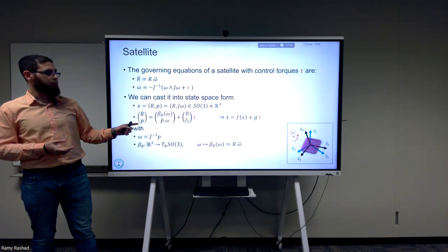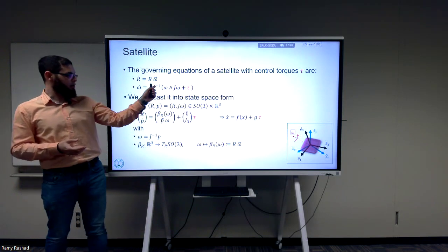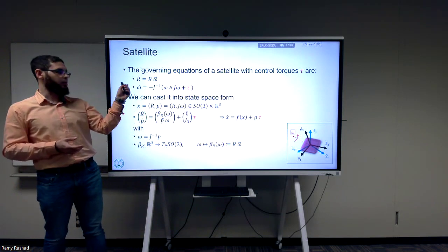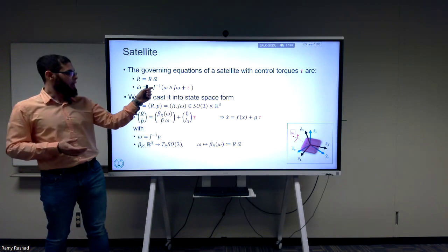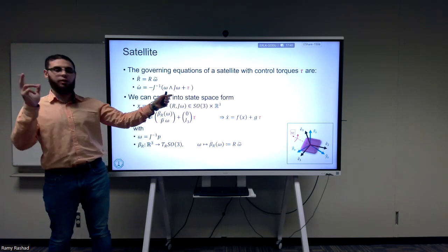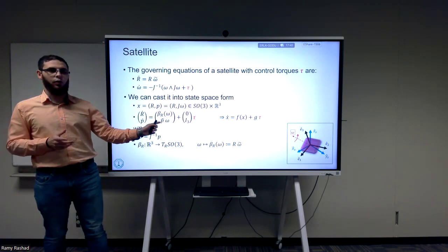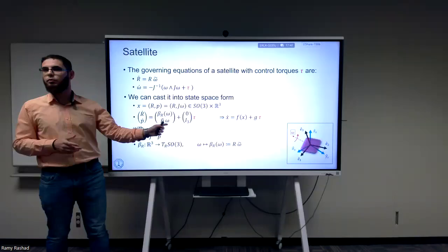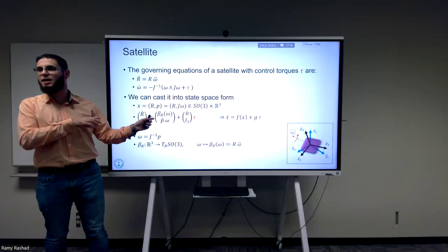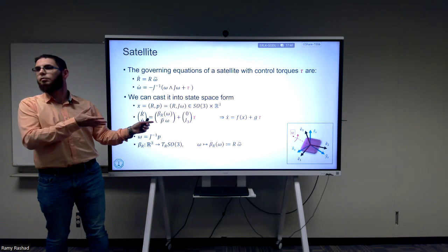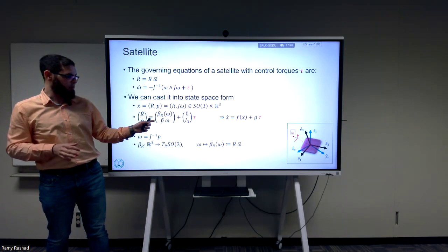And then the P dot, I'm going to rewrite, again, the J here is constant, so we're going to put it on the left-hand side. So P dot is J omega dot. And this term in the middle, I can rewrite it as the skew-symmetric form of P multiplied by omega, or the cross product of P multiplied by omega. And the P here is the angular momentum. Okay? Just to keep the physics in mind.